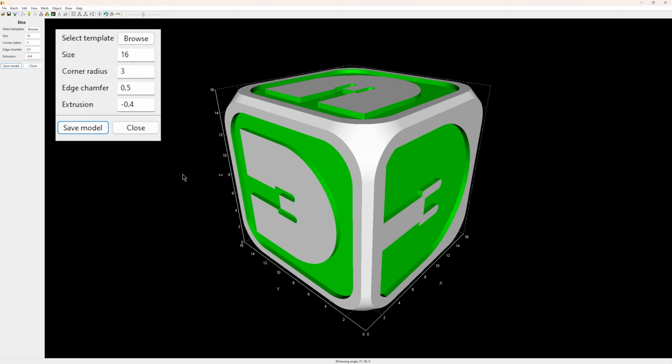If you wanted to go for the former option, having it flush with the surface, what you want to choose here is a distance that is smaller than both the size of your extrusion lines and your layer height when printing. This means that when it comes to painting in your slicer, there will still be a geometrical difference there, so you'll be able to use the fill tool to paint it in. But because the distance is smaller than your layer height, it will all be printed on the same layer still. For doing this, I tend to use 0.005mm, so here we'd use minus 0.005.